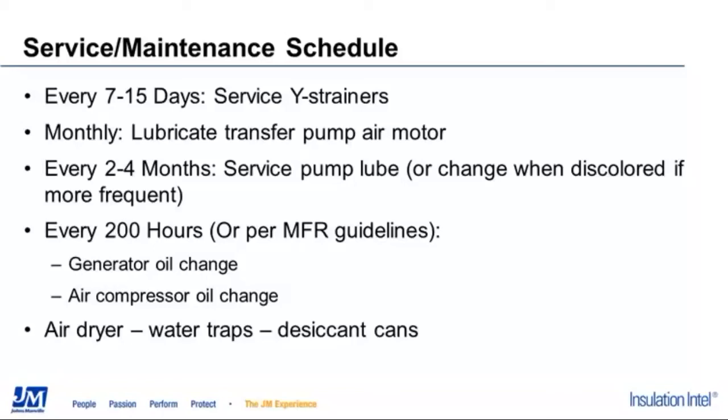They are the equipment manufacturer, but for us, this is based on a lot of history and experience. We manufacture a really nice, clean material. We don't have a lot of problems with plugging up Y strainers, and experience has told us that checking these every 7 to 15 days is sufficient for our material.